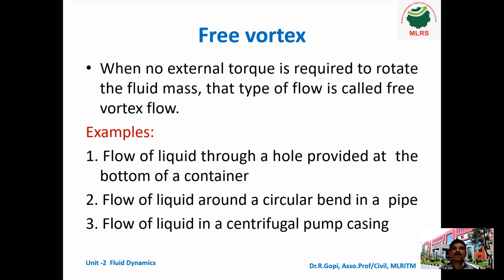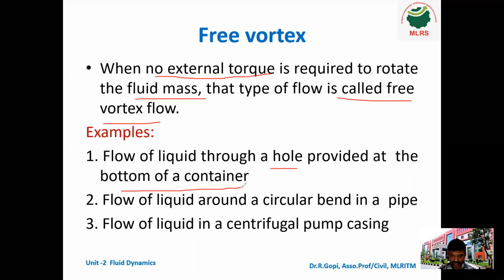When no external torque is required to rotate the fluid mass, that type of flow is called free vortex. Example, the flow of liquid through a hole provided at the bottom of the container or the bottom of the sink.